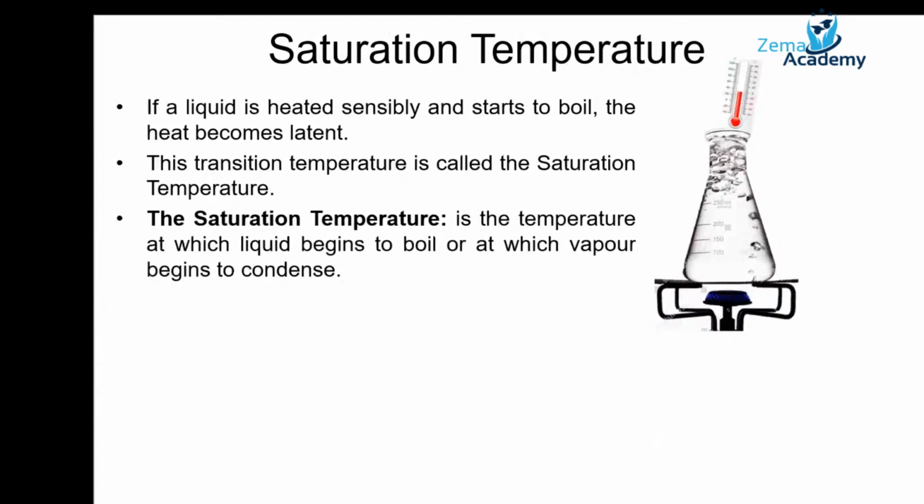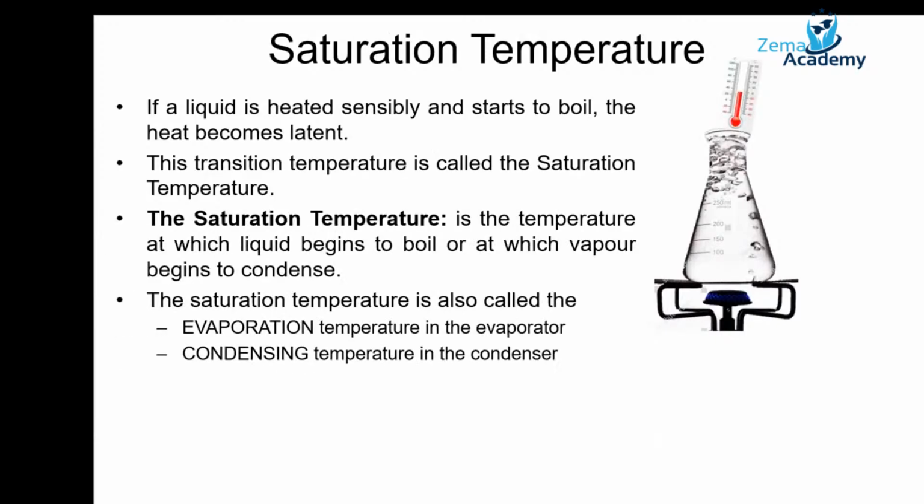Some terminology that we will be using is saturation temperature. This refers to the transition point. If you boil water, for instance, the point at which water starts to boil, that transition point, is what we refer to as saturation temperature. And we will use terms like evaporation temperature or condensing temperature. We are actually referring to the saturation temperatures. So we will use some of this terminology so you know what we are referring to.